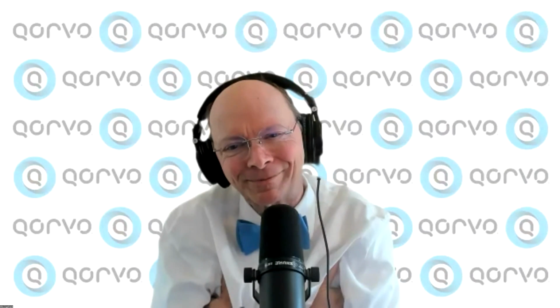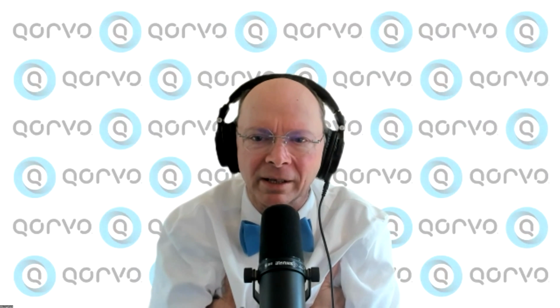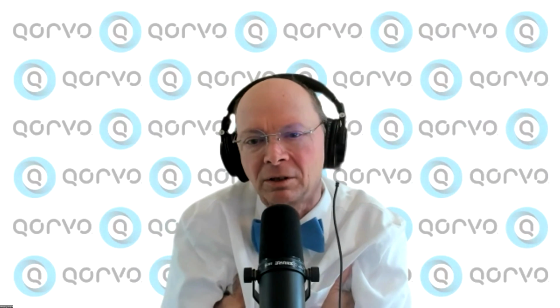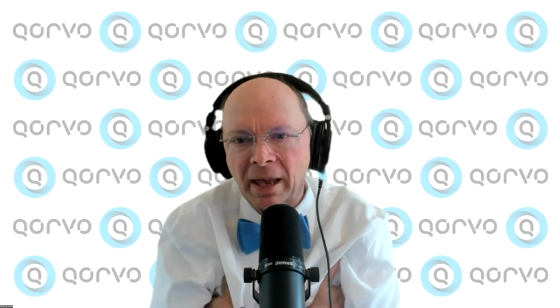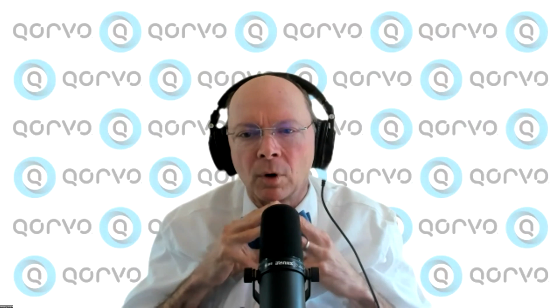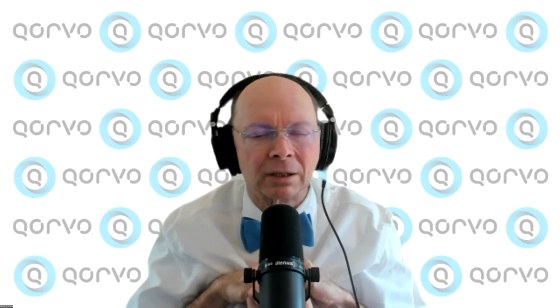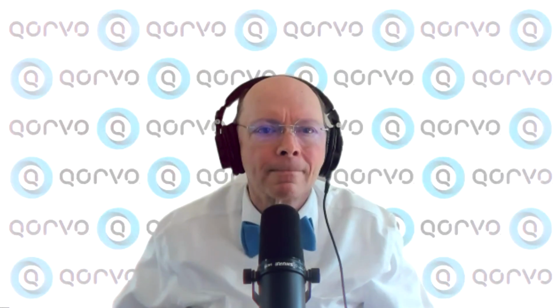Okay, and I still have a curve tracer over here. I have a couple actually. I have an old Tektronix and a Leader. Well, I have curve tracers, but I actually make my own because I want pulsed data. Even for a small signal FET, you need to pulse it because you can't let the temperature change. You have to fit the device equations with the transistor completely at one temperature. So even for small signal FETs, I use a pulser. I have a very high quality curve tracer. If you've got time, I can show you the schematic here if I can find it.